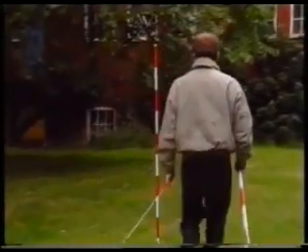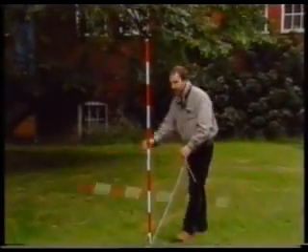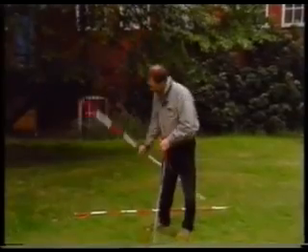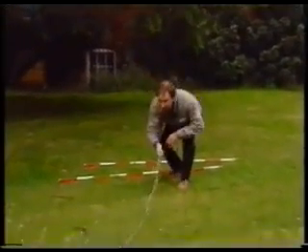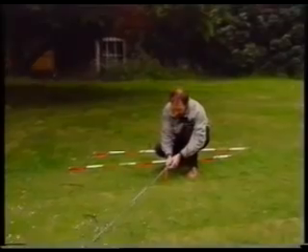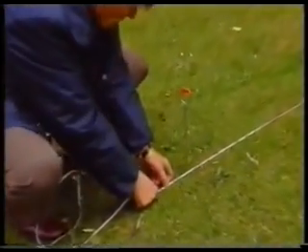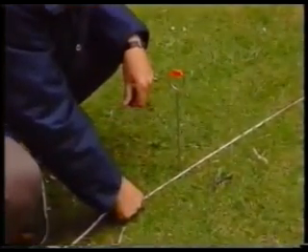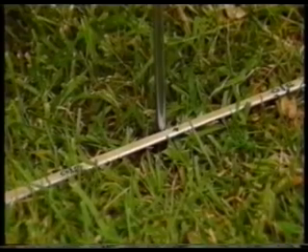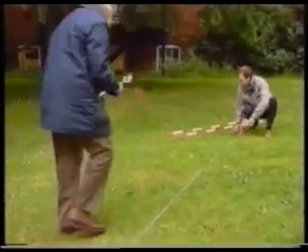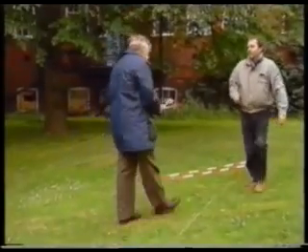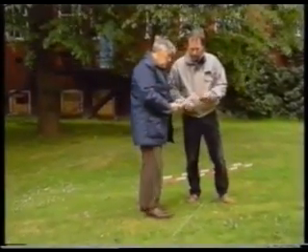Once this is done, the leader moves off and the follower picks up the marking arrow before also moving further along the line. The procedure continues until point B is reached, where the last measurement will be less than a complete tape length: 3.55 meters. The leader and follower now check the number of arrows that have been used. Okay, that's fine. Great.